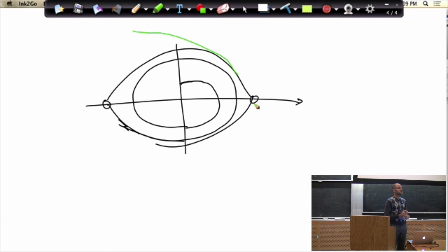Yeah, so our controller is only made to control the energy of the system, not its position. But the whole reason we selected this controller is because the entire homoclinic orbit has the same energy. So if the controller is good, you'll stay on the homoclinic orbit, but you have no guarantee as to where. So once you get near the fixed point, you need to switch to that linearized controller to stay there. Exactly right. So when you get here, if someone were to perturb me here, I will still stabilize the homoclinic orbit, but I'll go all the way around and then come back and visit again. But the second part is exactly right too.